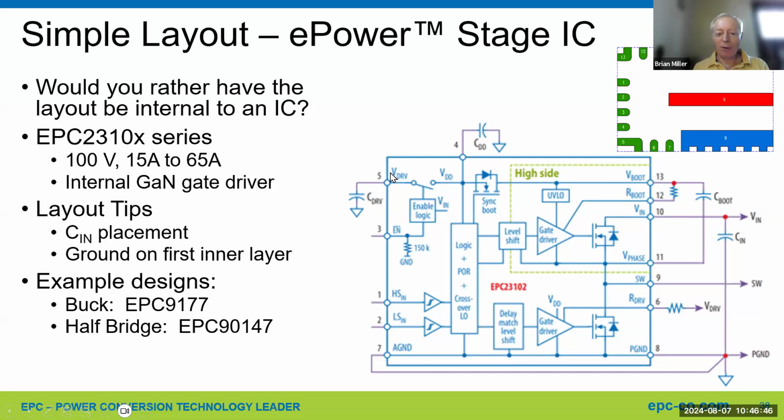Yeah, everything in this blue box right here is all one monolithic GaN IC. So everything in here is a GaN FET. These FETs are the power FETs, 100 volt FETs. Some of these are low voltage FETs. This one has to withstand both, so it probably isn't low voltage, but some of the parts inside the gate driver are lower voltage. You can have a difference of voltages within one GaN IC. But yes, this is a GaN FET in here.